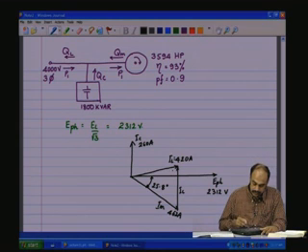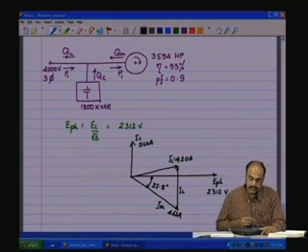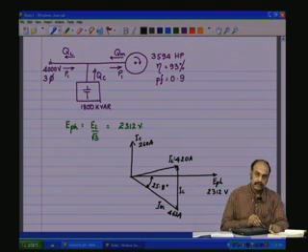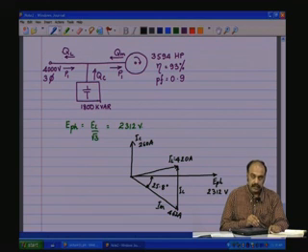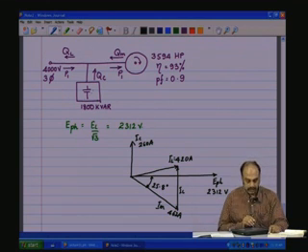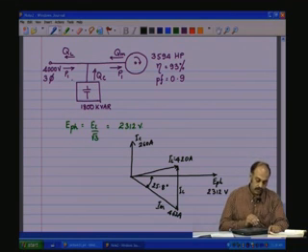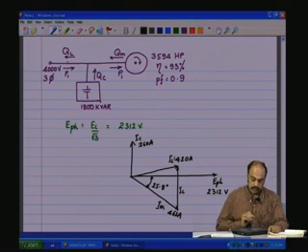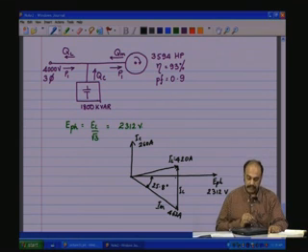Now, IL has a leading reactive component, because the reactive component on the line side is minus 405 kVAR, which is due to excessive capacitive reactance in the compensating network. So, more capacitive reactive power is being fed into the mains, and therefore this leading part. If this is adjusted, that could be made in phase.